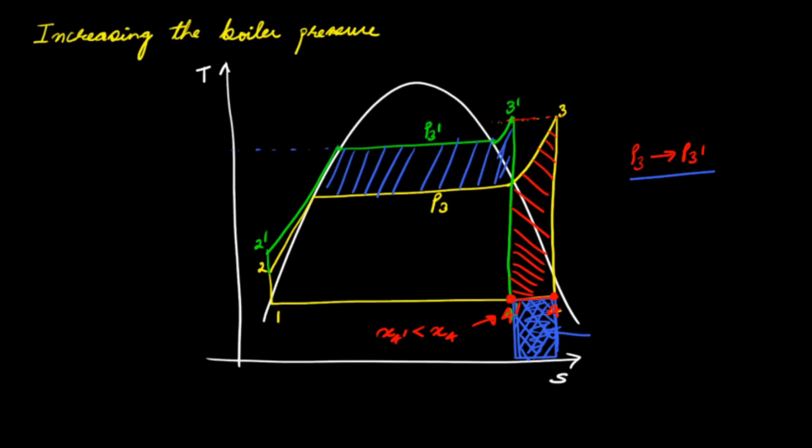It increases if we increase the boiler pressure, that is the maximum pressure. The efficiency also increases by superheating. However, only superheating results in an increase in the quality of steam leaving the turbine, whereas if we reduce the exhaust pressure of the turbine, or if we increase this boiler pressure, then the quality of the steam exiting the turbine will decrease, and that is not desirable.